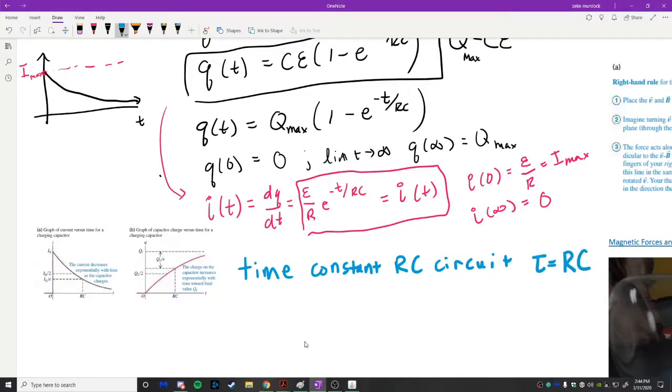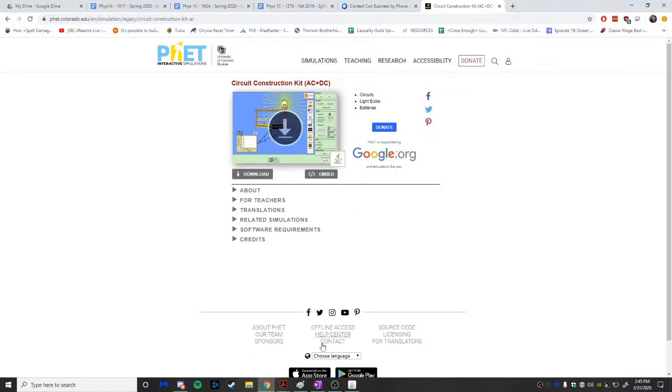So this quantity, R times C, the resistance times the capacitance, shows up right there in both equations, underneath the time, right? So an easy way to describe what's going on in a circuit like this is to simply multiply those two quantities and get an idea for the time that it takes to actually charge up. And you can use the quantities, for example, like we have over here.